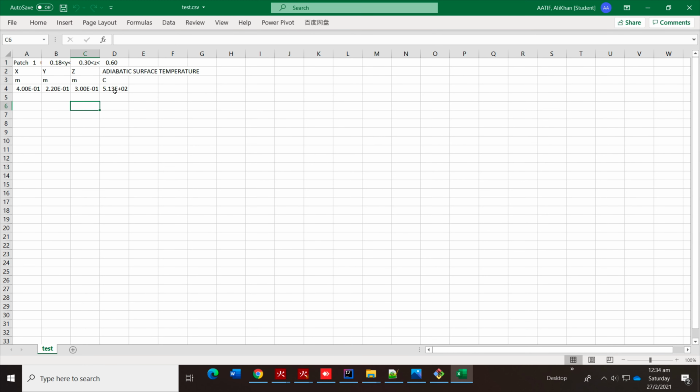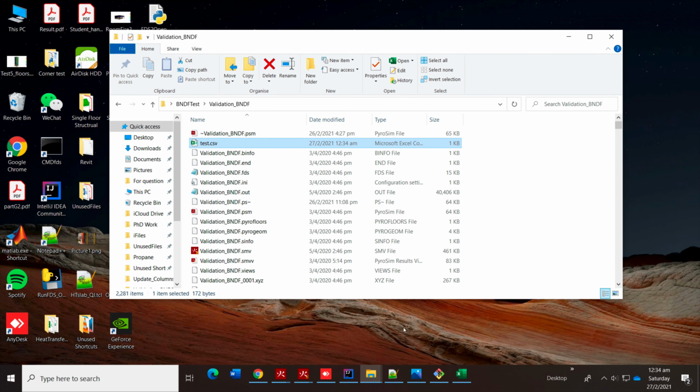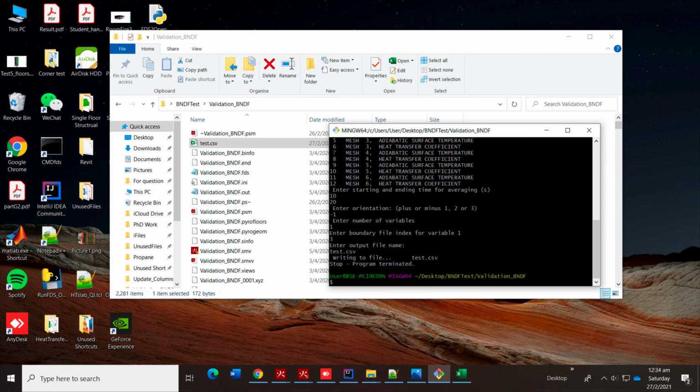Within these places, within 10 to 20 seconds, the average temperature I got is 512. It gives a bunch of other data also, which I don't need. I need this, but I have to make this data in OpenSees format. You cannot do this for each 10 seconds, 20 seconds, 30 seconds. Repeating this process would take days and maybe months if you have very large structures. If your fire is 3 or 4 hours, it would be every 10 seconds.